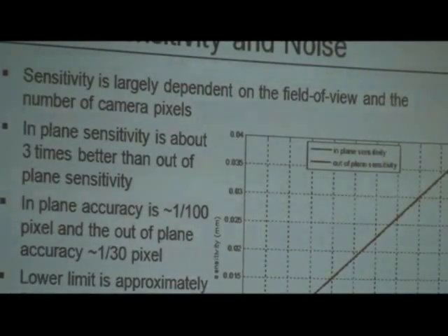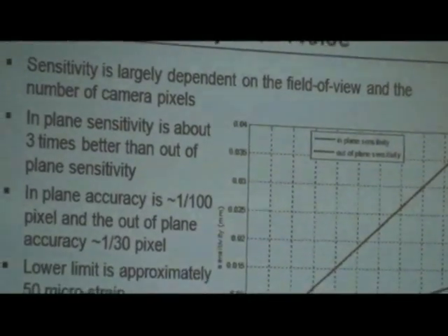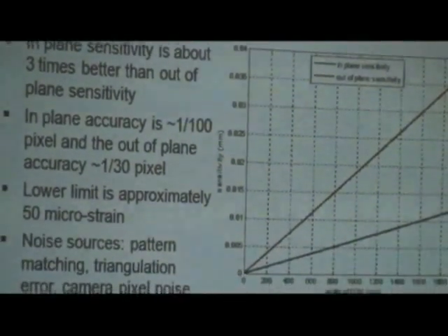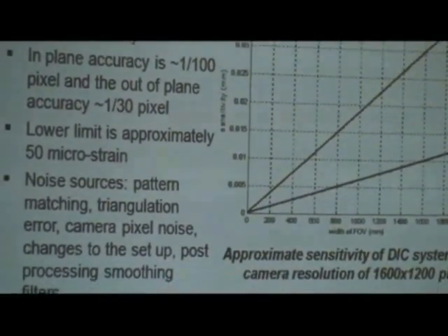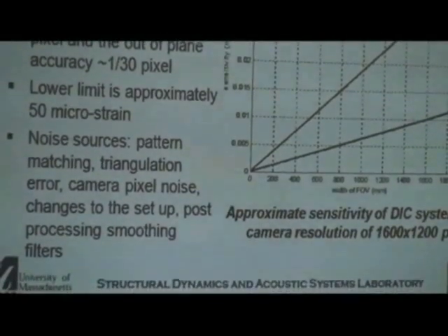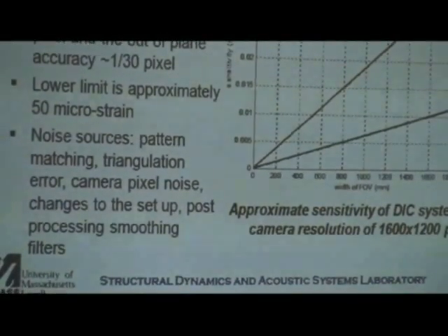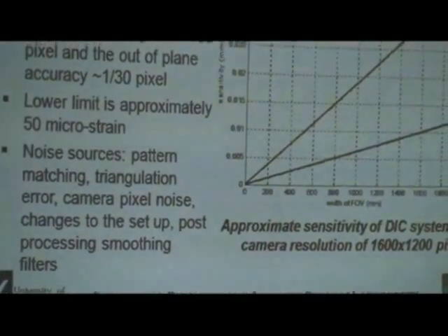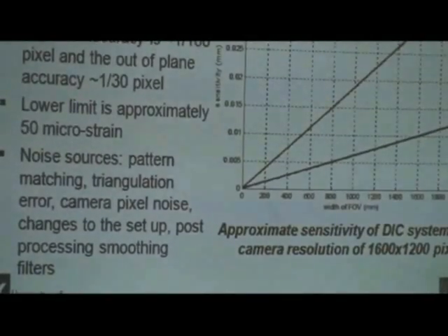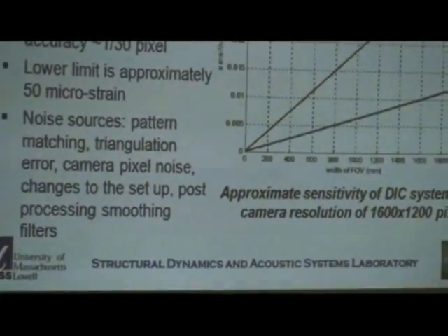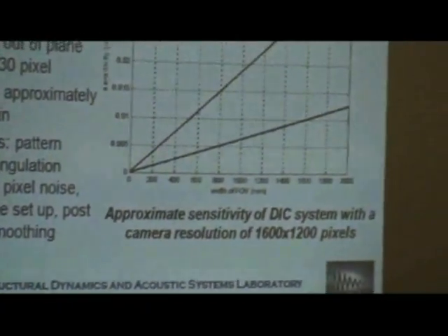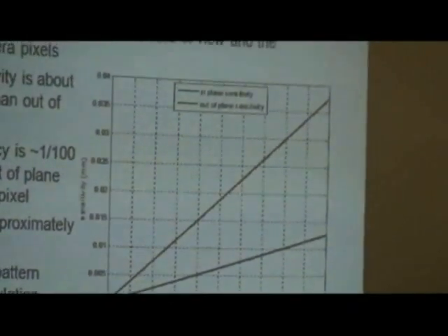So if I took an image that's about this large with my camera, I can detect changes in that structure to about 1/1000th of an inch. Now, it scales proportionally. If instead of 1.3 meters I made it 10.3 meters, then my resolution, instead of being 25 microns, is going to be 250 microns. And so it scales linearly.